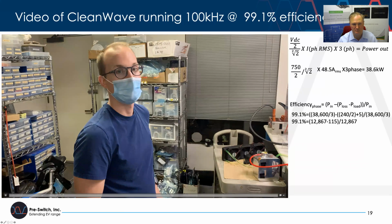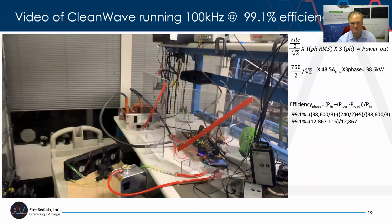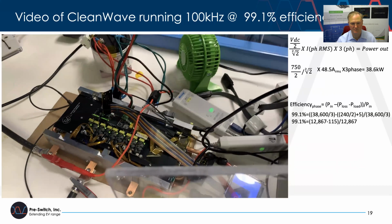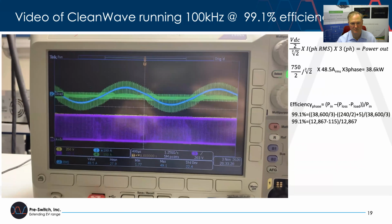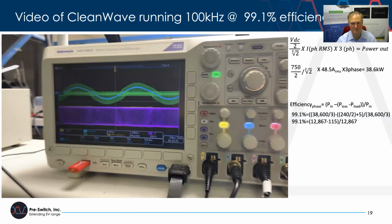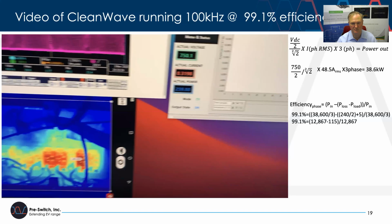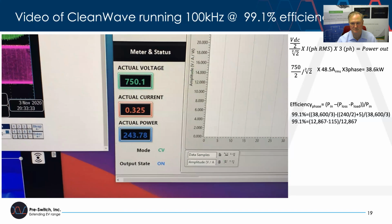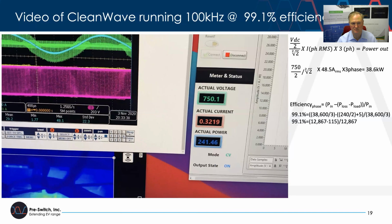Hey guys, this is Jimmy Palmer at FreeSwitch. This is our CleanWave 200 evaluation unit. We're running at 38.6 kilowatts, calculated 3-phase power in full bridge mode. We're running at 100 kilohertz, 500 hertz on the middle. And our calculated efficiency is 99.2%. That's based on the loss from the power supply. Since we're circulating the power, this is just the supply loss.